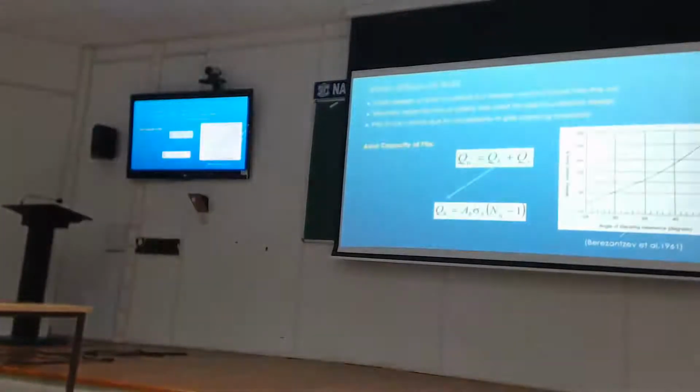What it is saying is that it's important that you estimate your friction angle reasonably well, because you can overestimate or underestimate your base capacity by factors of 10 easily. So if you're too conservative and said, oh, I can't be sure, and maybe my friction angle is as low as 25 degrees, then you end up with an Nq of only 15.